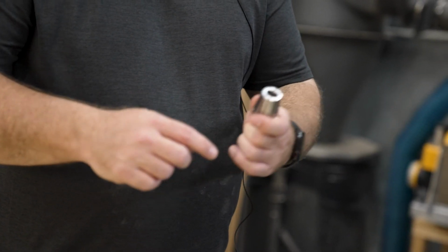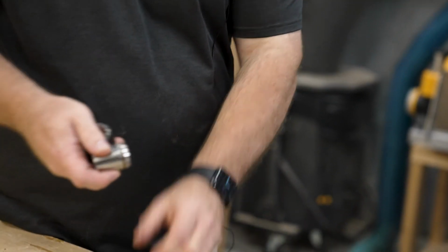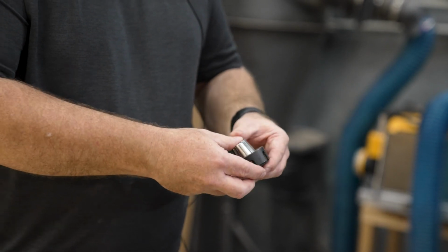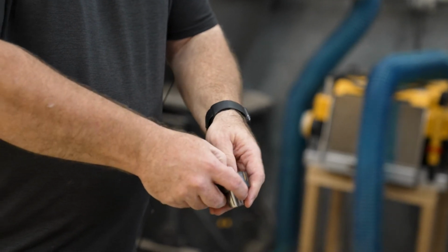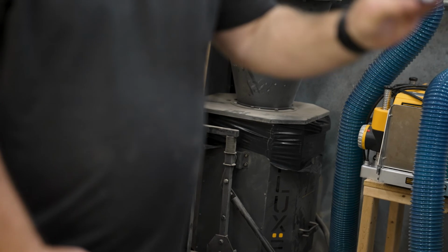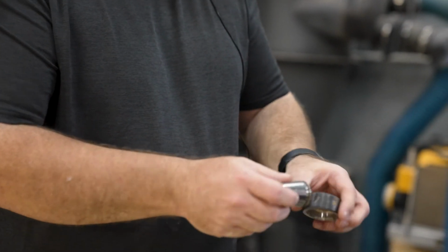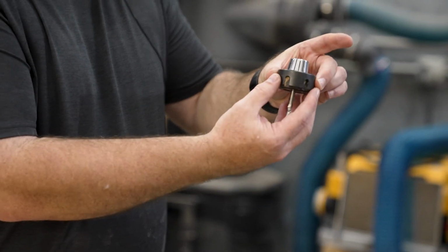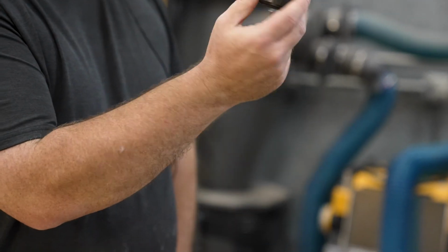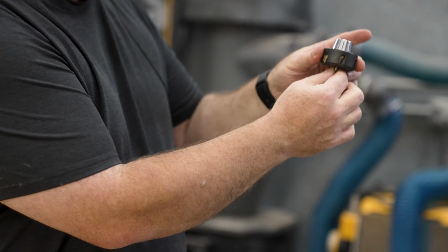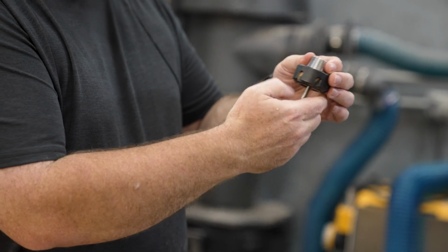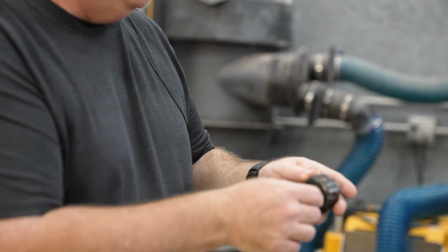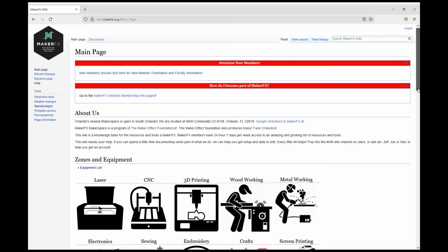The collet itself gets placed in this nut. Normally what's in the machine is the 1/4 inch shank and the 1/4 inch collet pushed into this nut. It just pushes in; you'll hear it snap. To get it out, you just push that guy out. There's a plastic container underneath the machine. We have 2 nuts and 3 different collets, so it's pretty easy to push the collet in. Then the bit will go in, and it'll hold it there so you can insert it in the machine. What we'll actually do is, this will be on the bottom of the spindle already, hand tightened, and then we will push the bit up and tighten the nuts. There are 2 wrenches we'll use to tighten the nut, and that causes the collet to clamp down on the shank and hold the bit in place. Everybody will get it; you'll have a chance today to actually mount that bit in the machine. This is well documented on the wiki.